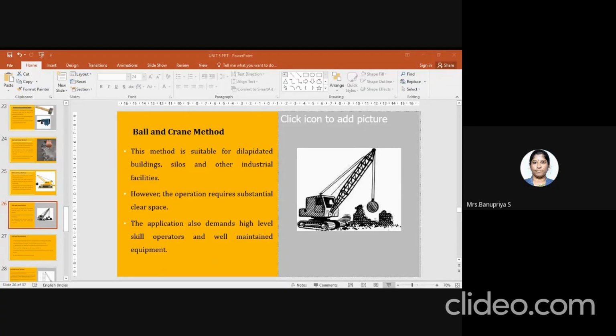And then another thing you have to consider is, before the demolition process by using the ball and crane, if you are doing the swing technique, as I said, you can do a vertical drop or a swinging line. When you do the swinging line, if there is any electrical pole line around the building you are going to demolish, it will cause some damages.